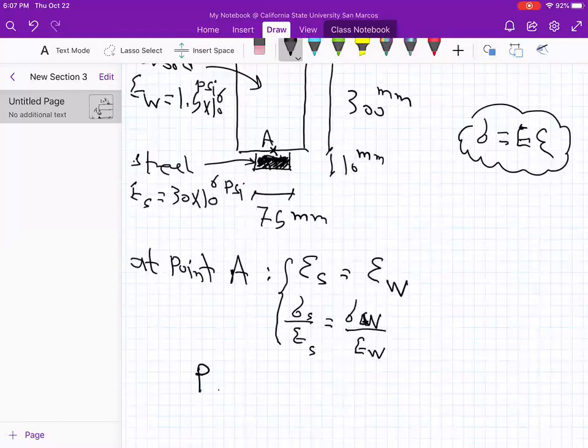So the P of the steel must be the same as the P of the wood. Now I'm starting the step to find the equivalent wood instead of steel. I want to temporarily remove the steel and put in wood to make a consistent material, a cross section based only on wood. At the end of the problem, we come back to see the effect of the steel.